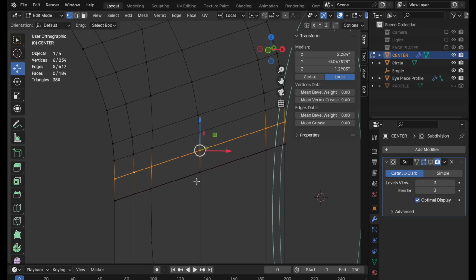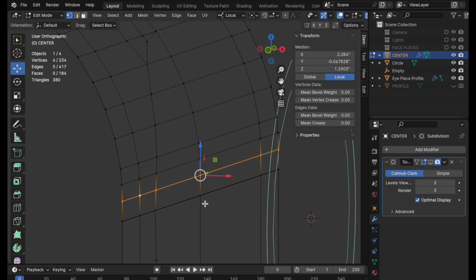And this is one of the reasons why up front, I wanted to make sure that I had sufficient resolution, why we went from 8 to 9, and then I added 2 more up to 11. It gave us just a little bit better curvature without really compromising and making it more difficult to match up the resolution of this shaft over here.